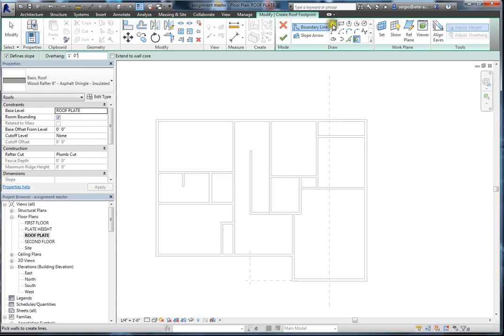And then we're going to use our sketch line to trace around our perimeter to match our roof plan. Now, over here, under offset, once I clicked on the line, I got a different options bar. Offset means that I need to put in a 1 foot overhang.